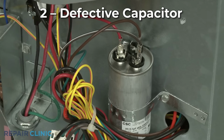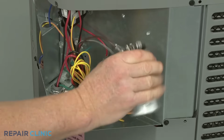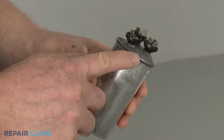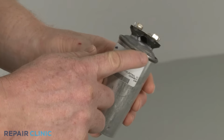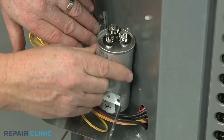A single-run or dual-run capacitor stores an electrical charge, then releases it to power the compressor or fan motor in the condensing unit. If the capacitor is defective, the condensing unit may be unable to cool. When a capacitor fails, it will often bulge or leak. If you observe any bulging or leaking, the capacitor must be replaced.